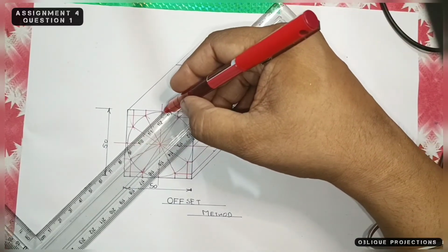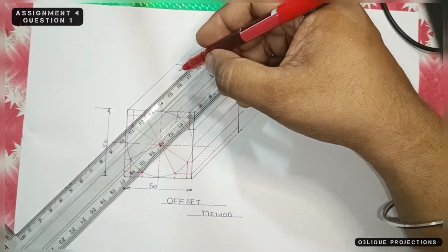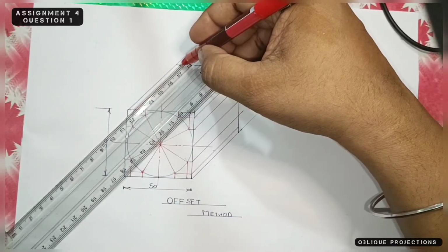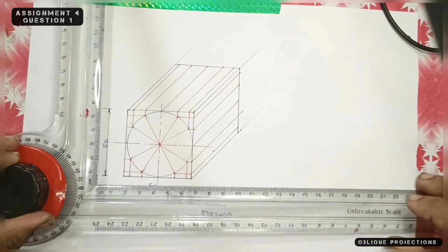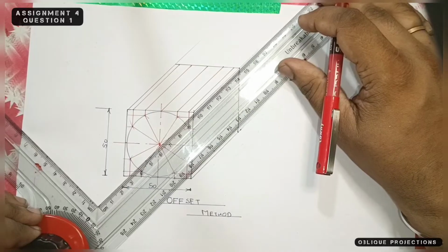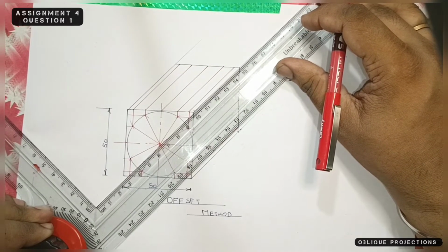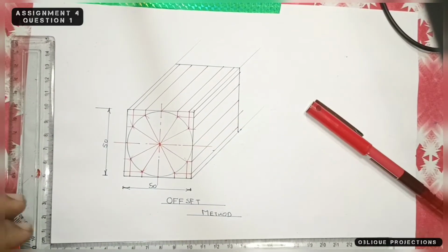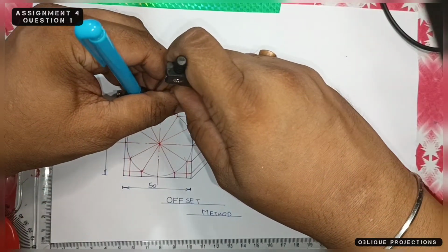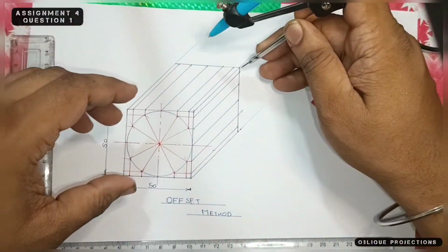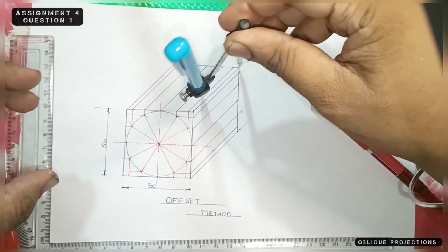Okay, so it is going to be 2 more circles over here on the top and the left side. So now what remains is you need to mark the rest of the points from here also. You need to put a compass over here and you open this until this mark and you mark it here.